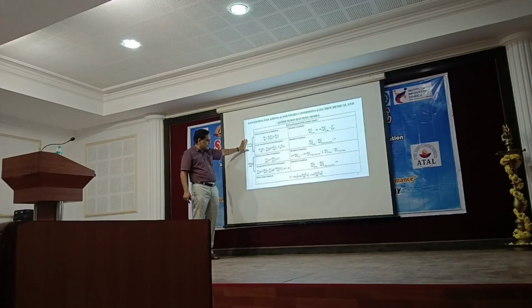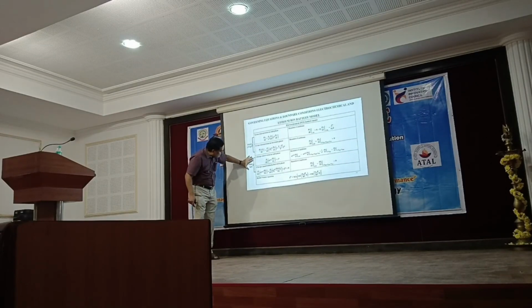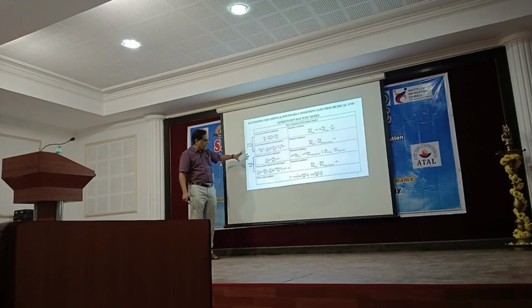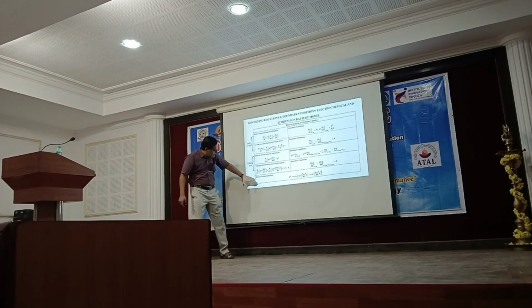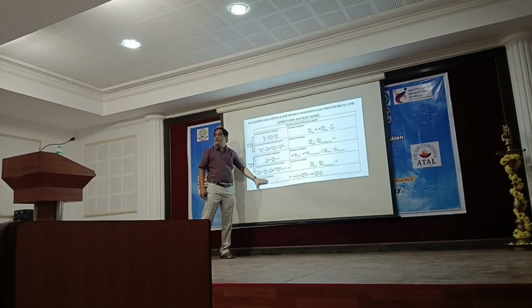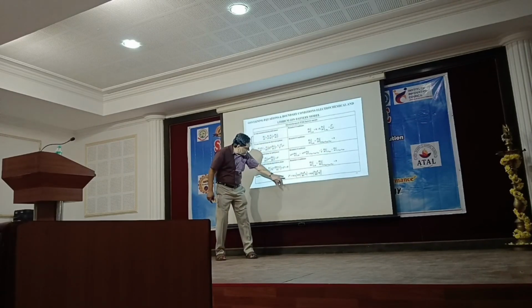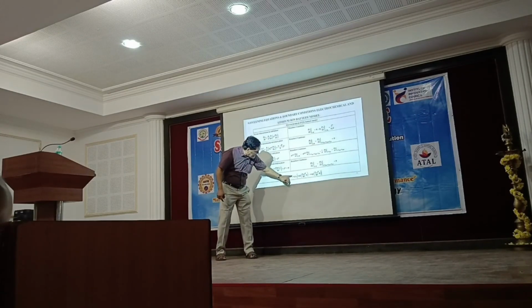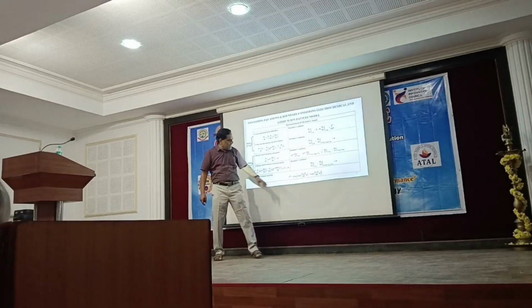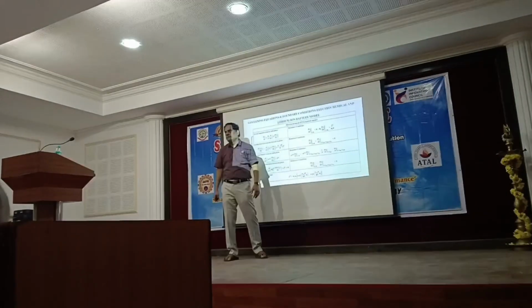It accounts for mass conservation, and charge conservation is taken care of through Ohm's law. Ultimately, by combining all, this is the most celebrated equation, called the Butler-Volmer equation. By combining all of them, it relates the current density for the battery, and internally we have overvoltage.